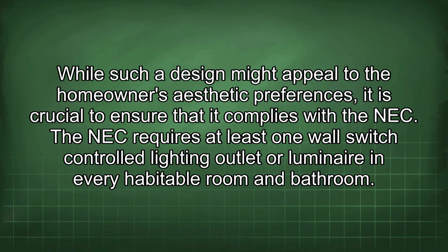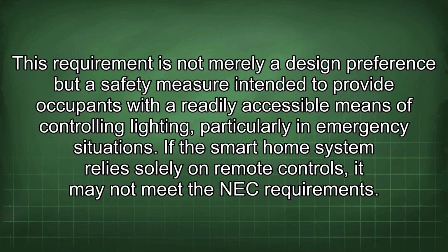While such a design might appeal to the homeowner's aesthetic preferences, it is crucial to ensure that it complies with the NEC. The NEC requires at least one wall switch-controlled lighting outlet or luminaire in every habitable room and bathroom. This requirement is not merely a design preference but a safety measure intended to provide occupants with a readily accessible means of controlling lighting, particularly in emergency situations.